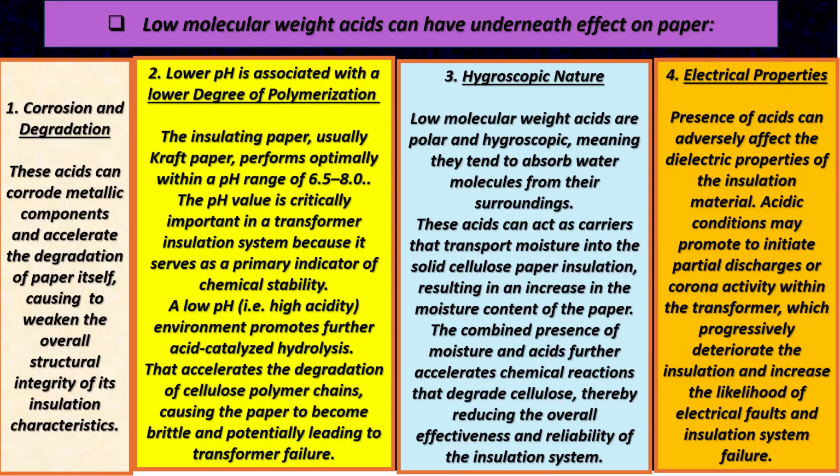Number 3, hygroscopic nature. Low molecular weight acids are polar and hygroscopic, meaning they tend to absorb water molecules from their surroundings. These acids can act as carriers that transport moisture into the solid cellulose paper insulation, resulting in an increase in the moisture content of the paper.